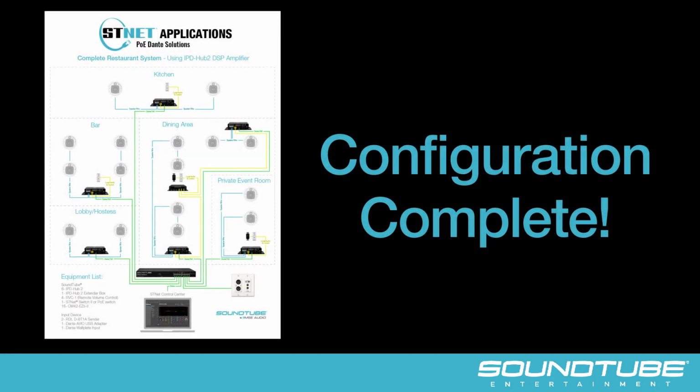We've now configured the entirety of the restaurant system. Across the 5 zones, we can play whole house audio or music directly from the laptop through the Avio USB device. This audio can be ducked out at any time by using the paging function through the Dante wall plate. Additionally, we have remote volume controls set up in the kitchen, bar, private event room, and dining area zones. This allows for independent control of our whole house audio.